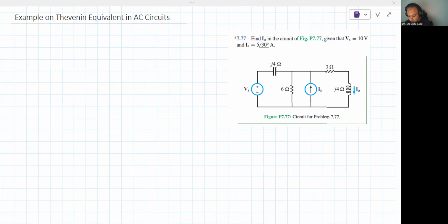So again, take any element in the circuit, and you can solve the circuit using that element, by reducing the whole circuit other than this element into two things: a resistor or a reactance in general, and a voltage source or current source. In Thevenin, it's a voltage source.